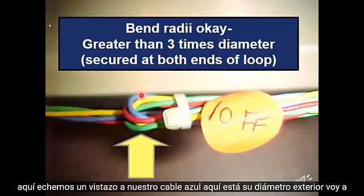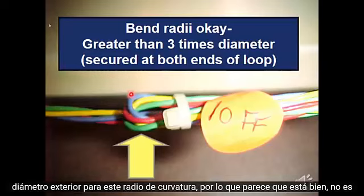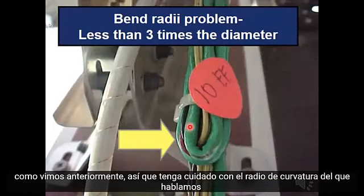So here let's look at our blue wire. Here's your outside diameter. I'm going to just eyeball this one and say we've got 1, 2, 3, maybe 3.5 the outside diameter for this bend radius. So it looks like that's okay. It's not crushed too much. But now look at this one. It's basically folded in half, just like we saw earlier. So please be careful about the bend radius.